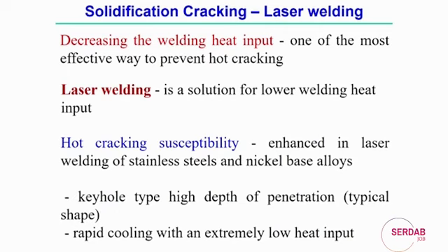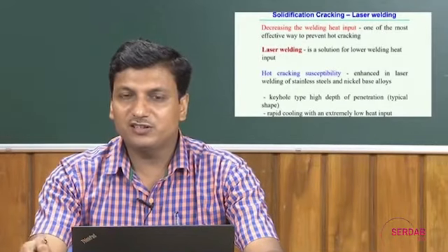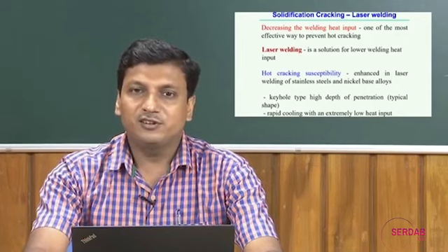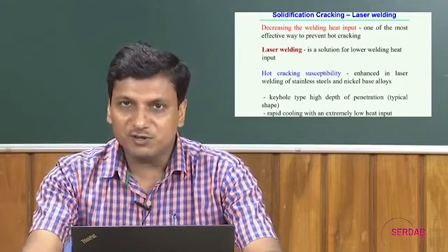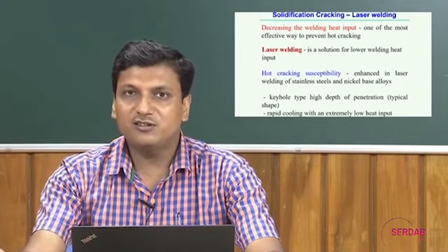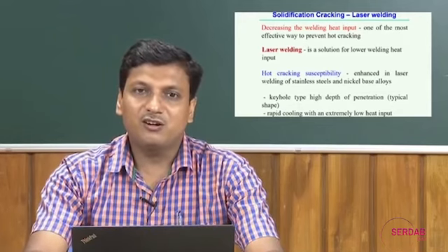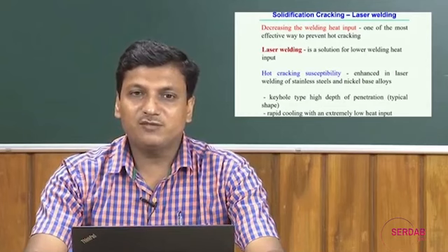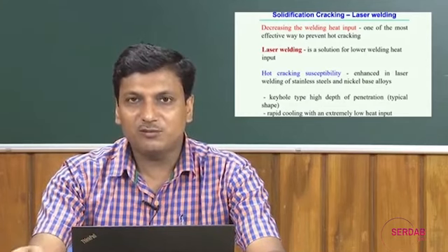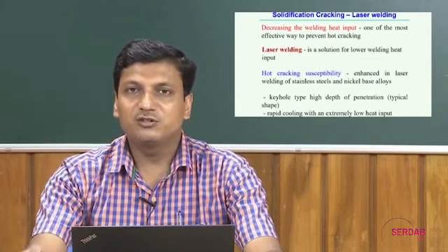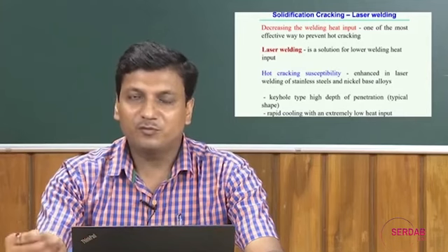Hot cracking susceptibility can be enhanced in the laser welding process also, in the case of materials like stainless steel and nickel based alloy. Even with lowered heat input, for these specific materials the laser welding process can still be susceptible to the hot cracking phenomena. In laser welding, the mode sometimes produced may be keyhole type. In that keyhole type, the depth of penetration is very high. The typical shape of this also promotes